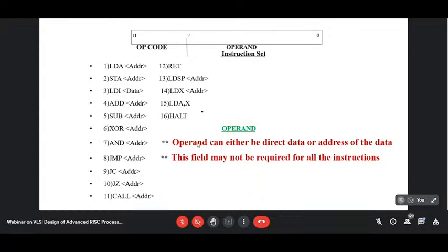So here, so far, we find that accumulator is one general purpose register. Now, since the CPU will execute the instructions one after one, that means there must be some counter which will keep track of the current address of the instructions, and this is known as a program counter. So it's a counter which keeps track of the address of the current instruction. Okay. So this is a special purpose register. So program counter is one register which will be required.